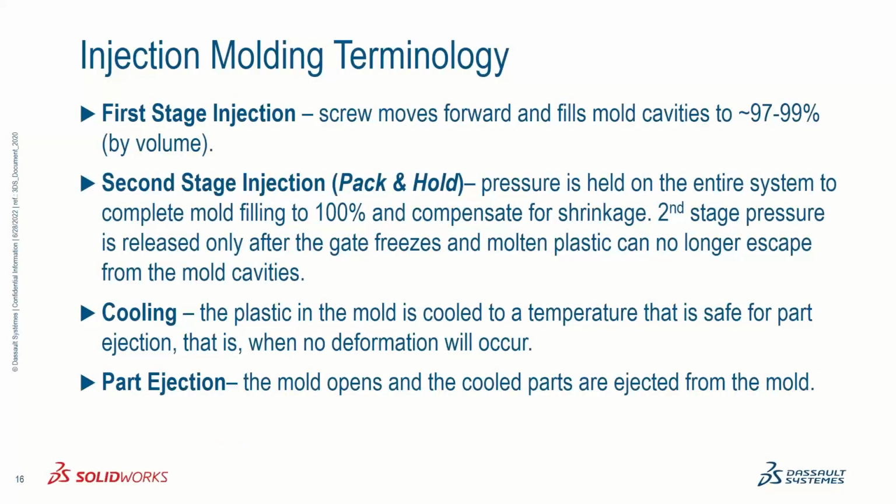Some quick injection molding terminology, because we'll be referencing it during the webinar. The first stage, injection, also known as the filling phase, is where you're rapidly injecting polymer into the cavity, into the mold. This is very fast, typically under 2 seconds.